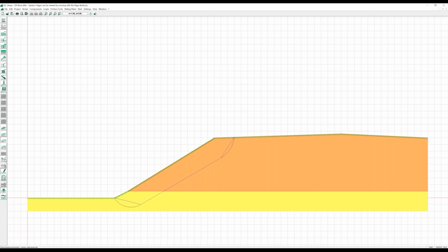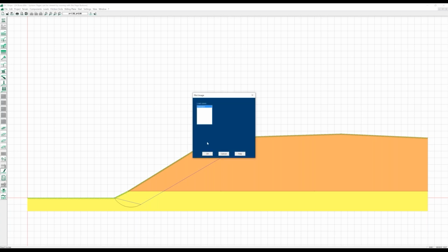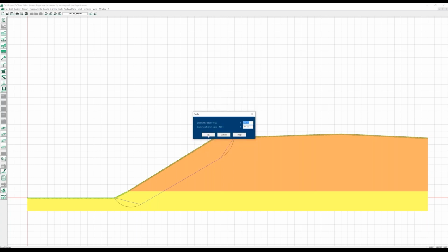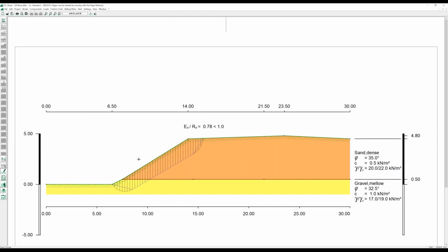And we can calculate this type of friction area, and this, for example, gives a little smaller utilization than we had before with 0.8. For this kind of friction area, it is quite complex to make an iteration for finding the minimum safety.